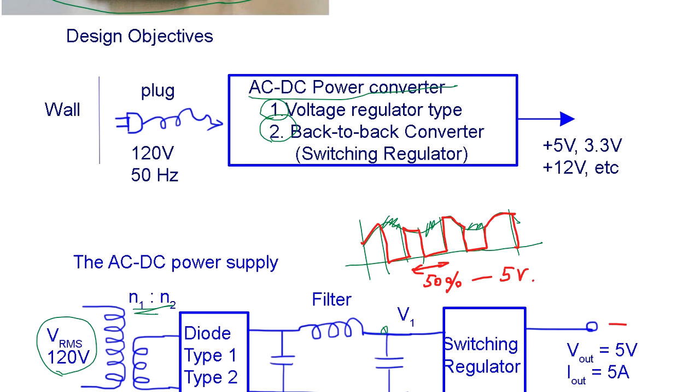And if the load increases and voltage starts dropping, then the time slice changes to say 60%, pumping more charge to the capacitor. So you can guess there is an output capacitor inside the circuit, pumping up more charge to maintain the 5 volt.